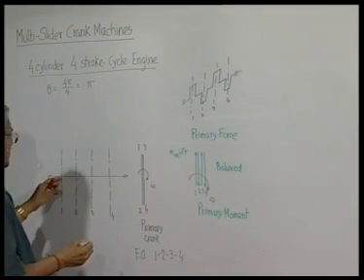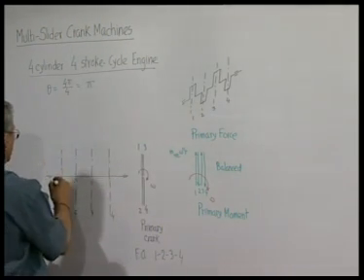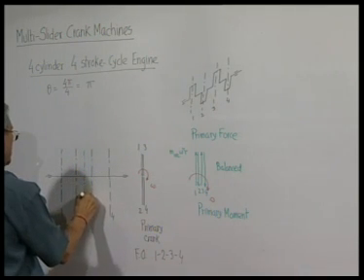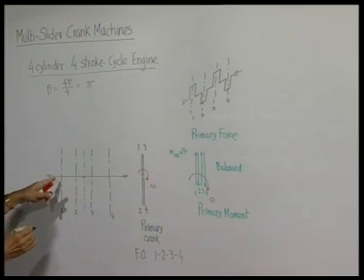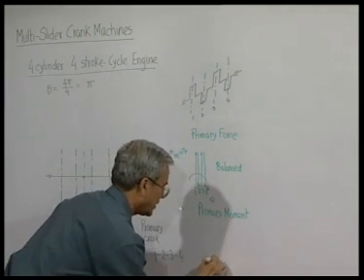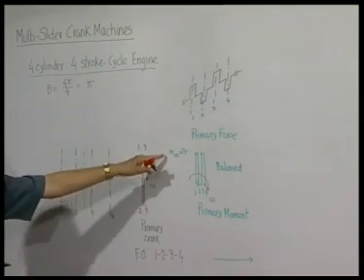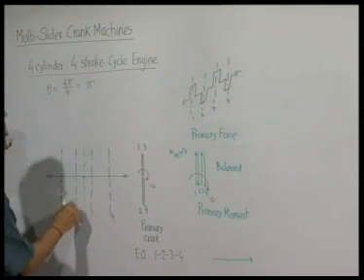So, for number 1, it is in this direction. Since this is the cylinder's engine center line, this is the point about which we should take the moment. So, this will produce a moment in the right hand direction whose magnitude is known, this into 1.5 a. Then this one is in the downward direction.